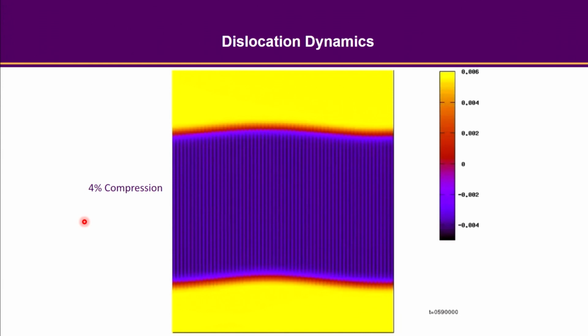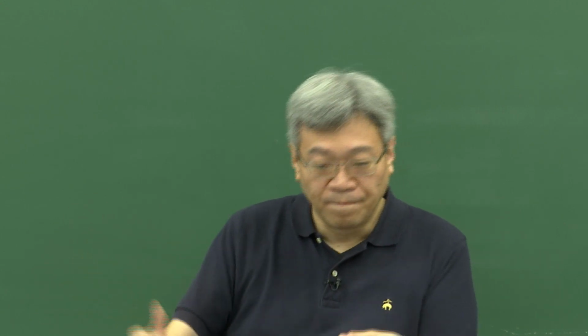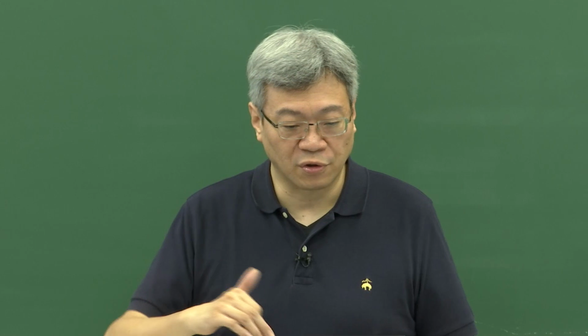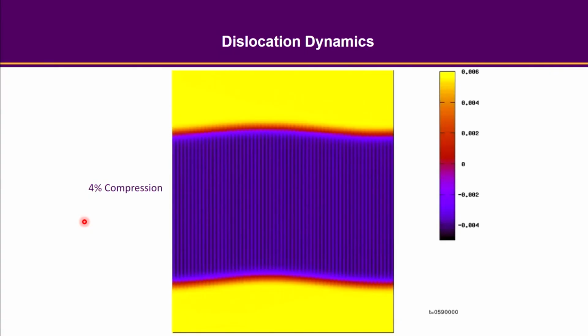Okay, so here is just to give you some idea what you can do with the phase field crystal. The concept is that we know the PFC can capture the elasticity well, so the system can reach the local mechanical equilibrium at the diffusive time scale. The system also captures a realistic solid-liquid interface. So based on those two properties, you can choose proper material problems to work on. ATG is one of them.